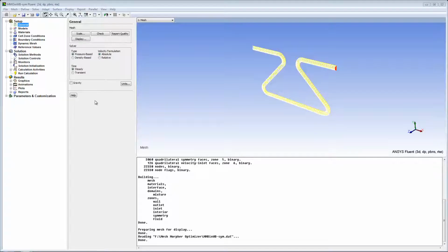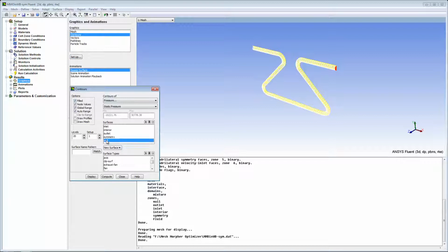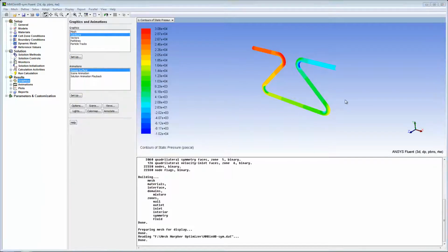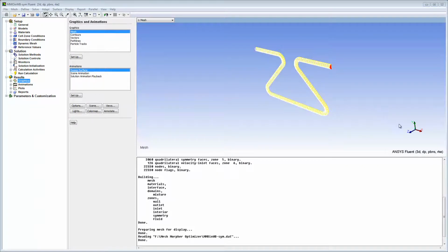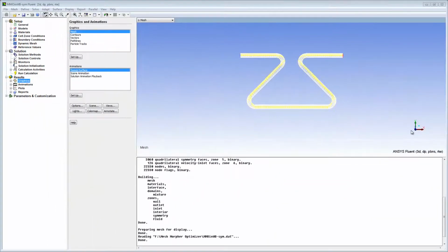Let me show you how to optimize the geometry of a Coriolis flow meter for reduced pressure drop through the system. I've already obtained results for the flow simulation through the tri-shaped tube using standalone Fluent. Only half of the geometry is considered because the tube is symmetrical. I want to investigate how the geometry changes in this portion of the tube will influence my target criteria for minimal pressure drop through the flow meter in order to select the optimal design for my system.